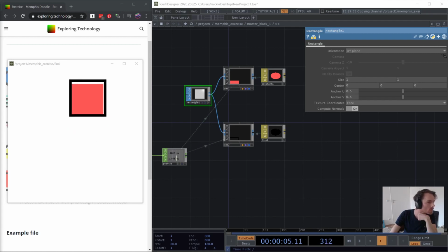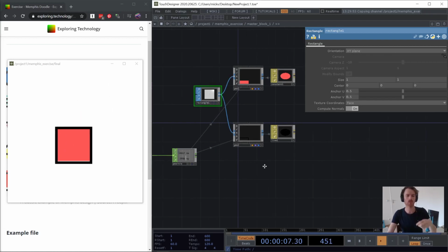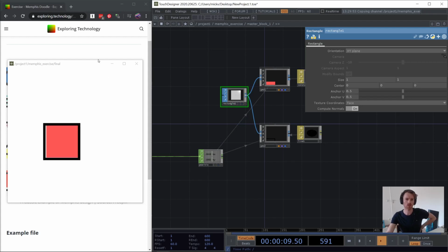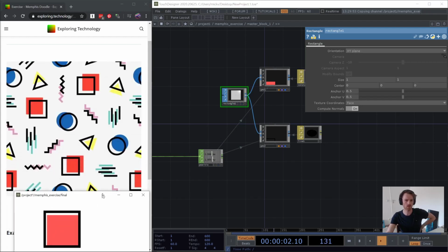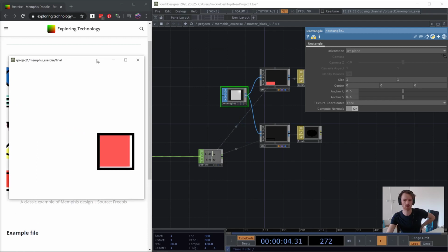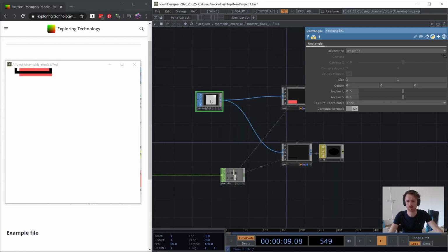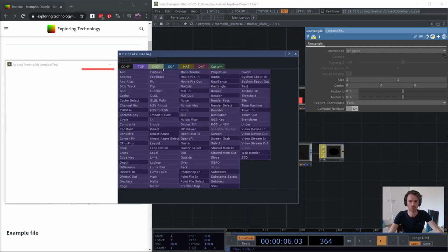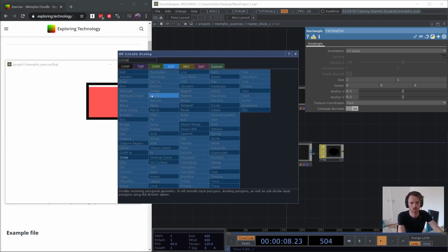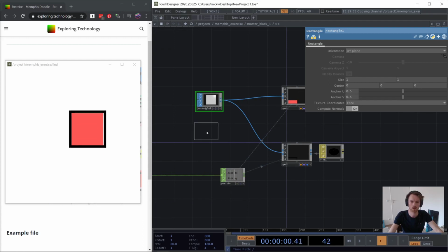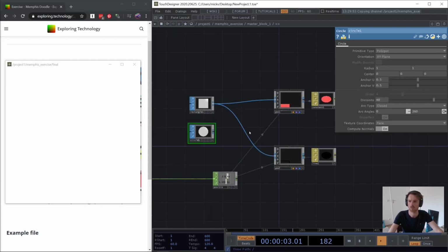So yeah, what you guys noticed was that we have different kinds of objects, right? So let's add a second object as well, like this circle, for example. And to do this, what I want to do is create a switch here that switches between the circle and the rectangle for this geometry. So first off, I'm going to create a circle sub. I have that done over here. And I'm going to set its radius to 0.5 on the X and Y.